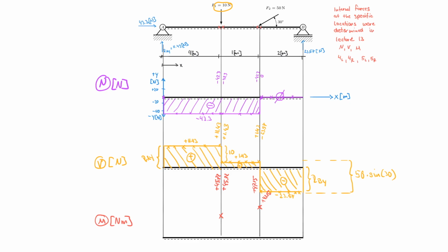What that also means is that at A, the lever arm is 0, and so I actually already know the next value. I know that this must be 0. And of course, you could have told that before, because we have here the hinge indicated, right? So this point here acts like a hinge. Sometimes teachers are not as nice as I am to give you actually the circle here, and they just assume that you know that the moment there is 0. But the reason I'm giving you the circle is to remind you that the moment there must always be equal to 0. And therefore, I also know that it must be 0 here on the right side, under B.